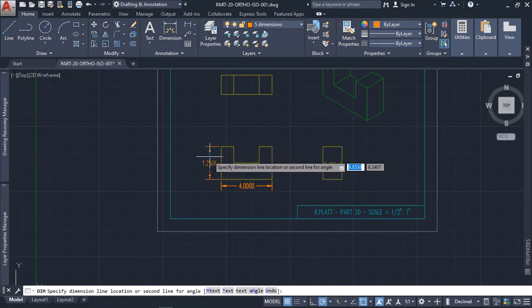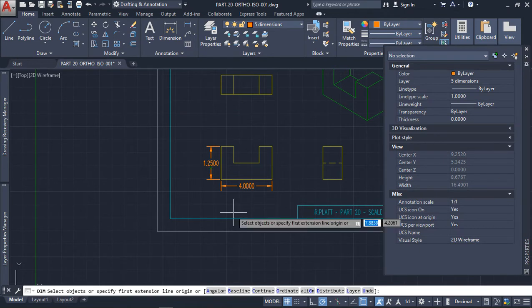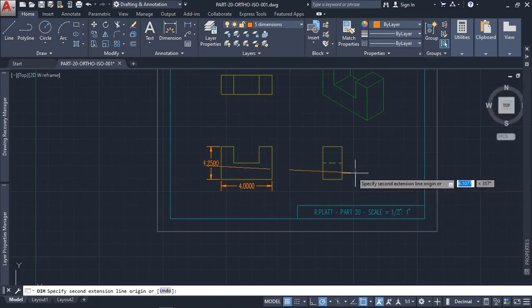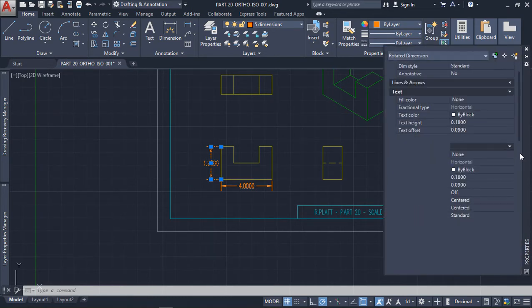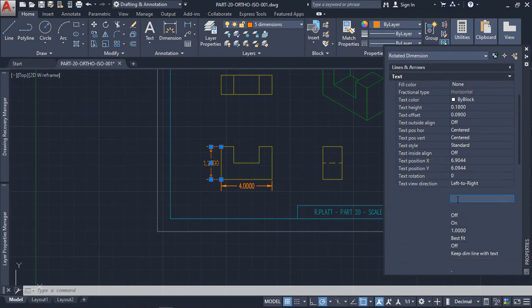Come out here to the right, and again we'll go 0.5, so that way we stay consistent on our dimension string length. Okay, now, again, it's got this set up here. We'll go back to properties. We're going to come down to, got to select it first. Whoops, still in dimensioning, so escape out of that. Select it, properties, scroll down to text override, key in 2.5, 4 decimal places, enter, escape.